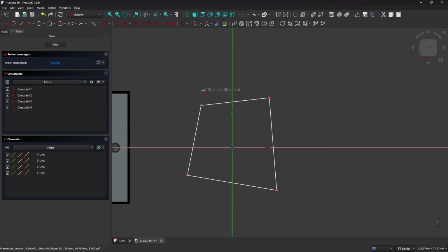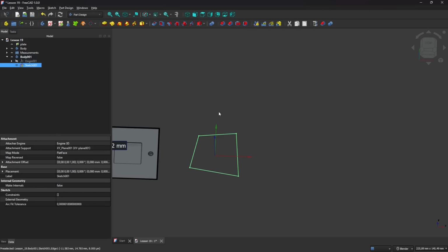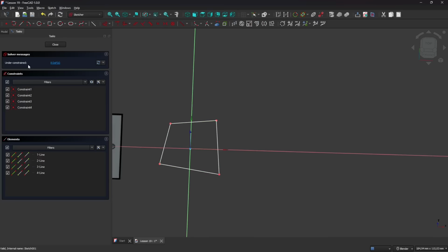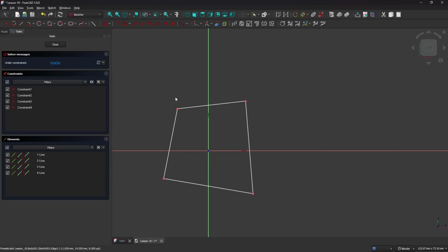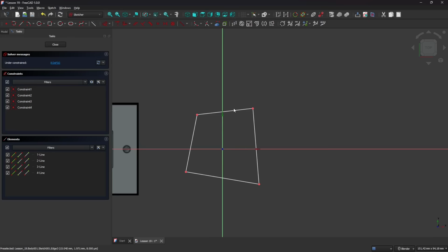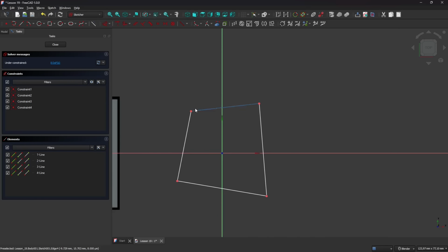Now, if you press the ESC key on the top left or your keyboard, you're going to exit the sketch. But let me just go back, double click. So if you press it one time, you're going to exit the command. If you press it 2 times, you're going to exit the sketch. So I want to exit the command and not the sketch. So now I am outside the polyline command and I can do something else.